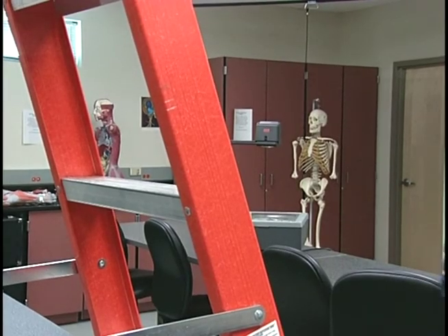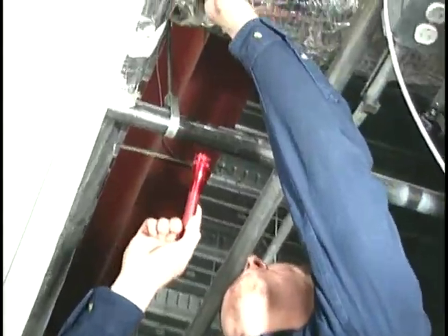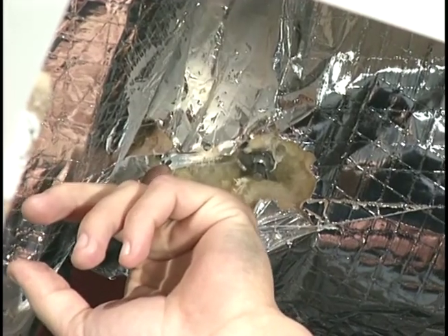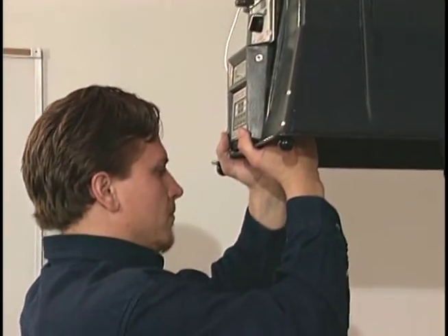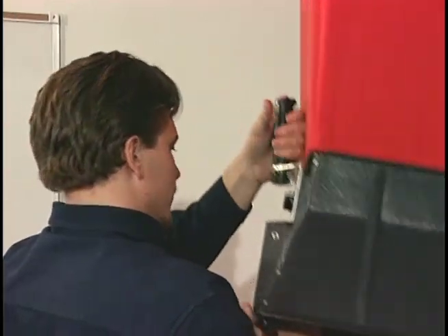After all the outlets in the system have been adjusted, it still may be necessary to make slight adjustments at the branch dampers in order to achieve the total system balance. As all the outlets have been balanced to each other by branch, an adjustment at the branch damper will increase or decrease all outlets on that branch proportionally.